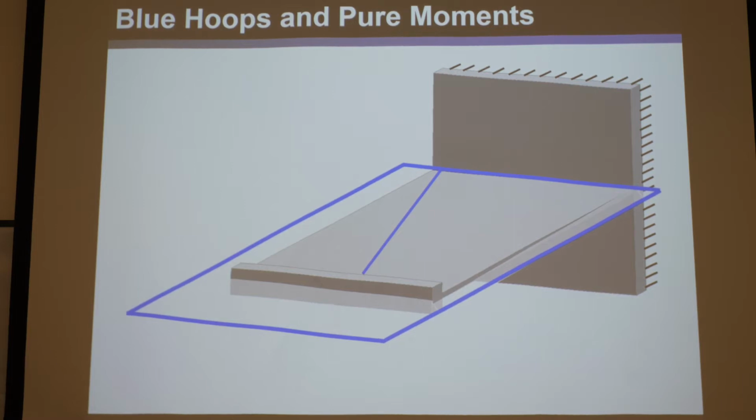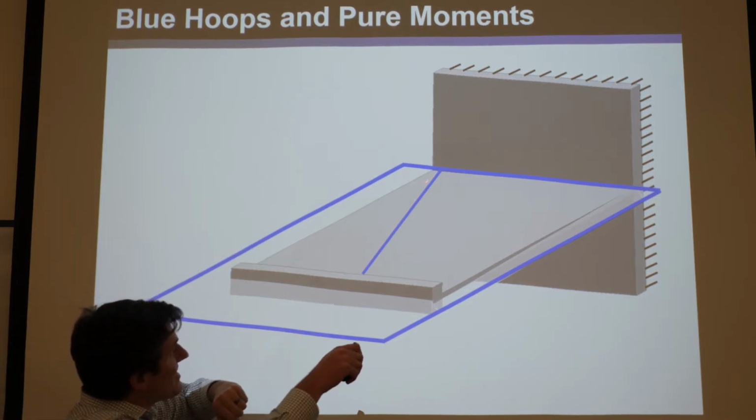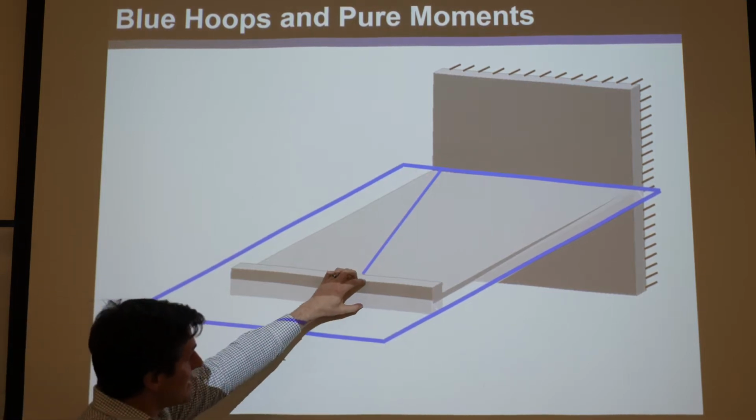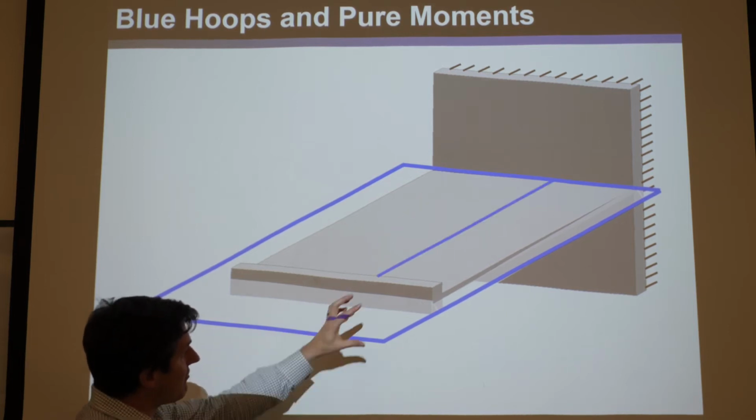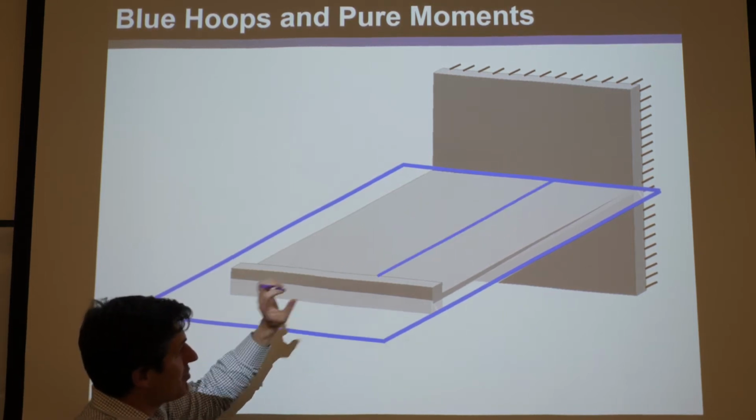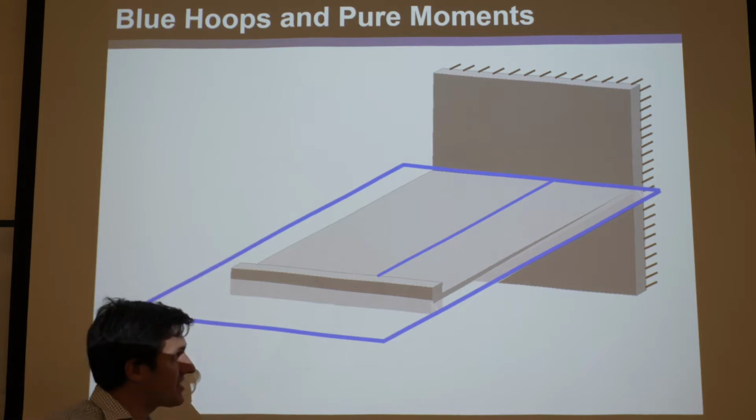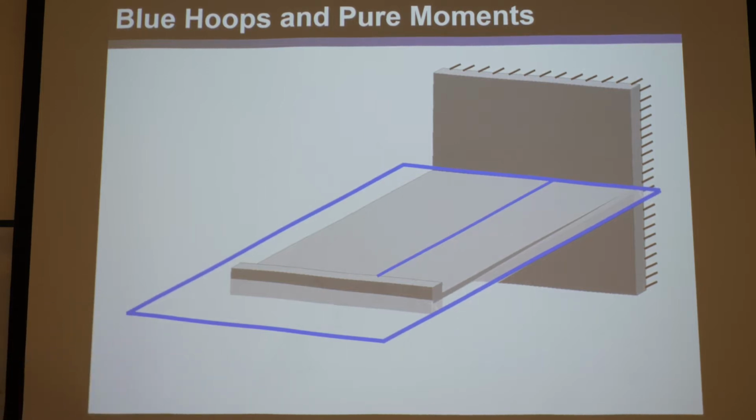Okay, so I want to teach you now a different way to think about constraint spaces. Maybe you've already been thinking of them this way, but they're essentially a space that represents all the loads that the constraint is capable of resisting given its geometry. Okay, so you can think, well, could we resist this pure force along this axis? Yes, that stage could. Could it resist that force? Yes, it could. That blade flexure will cause it to resist that force. Okay, what about that force? Yes.